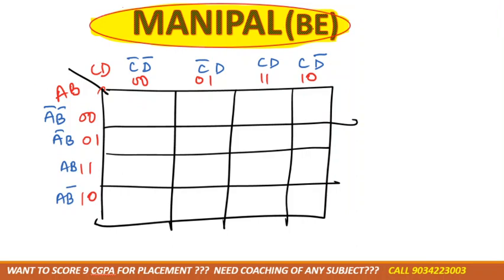Now I am telling you the maximum possible, like 1, 1. Now tell me, will these two become a pair or not? These two will become a pair because they are in the same column, right? Now suppose we have 4 ones. Now what will you do? Make a pair of 2 ones or a single pair of 4 ones? 4 ones.